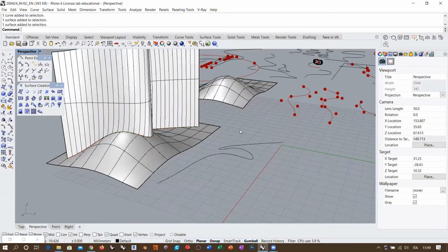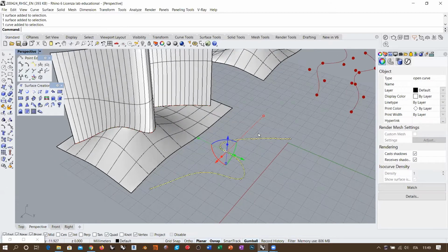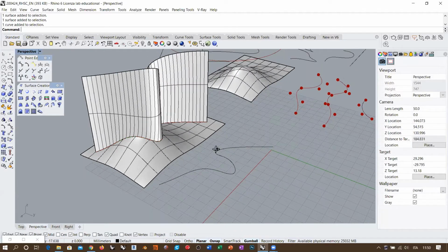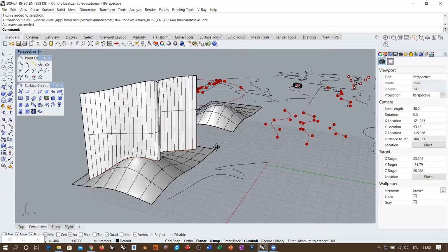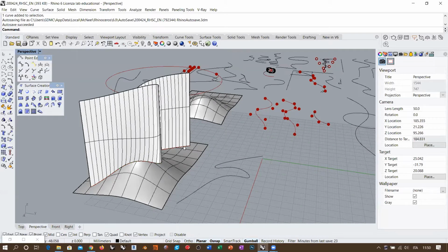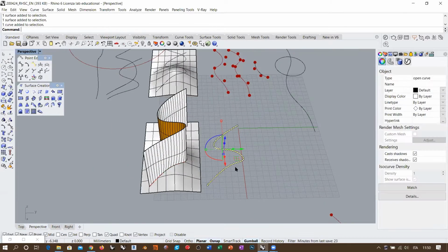But if we, for example, repeat this with less precision, so with fewer control points, then from this intersection you will get separated segments for the intersection. So this could be one problem. I'm not going to repeat the loft, but you can try this if you want. You can simply decrease the amount of control points for your rebuild, and take into account the value for the maximum deviation. But in that case, just performing this intersection would result in separate intersection lines. So not in this case.